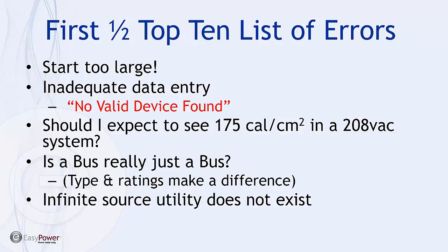So the question is, if you see large elevated energies, there are basically 2 approaches. One is they could be realistic insofar as if the energy level supplying that voltage is greater than 125 kVA, I would be careful how I tweak the calculations before I understood the currents involved. And there are adjustments in the tool that allow us to limit the amount of time the calculations are conducted if we are less than 125 kVA supply.